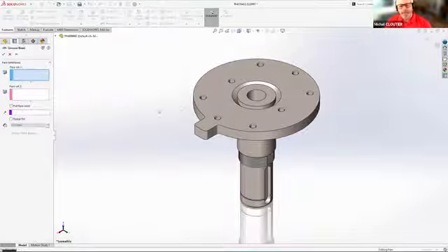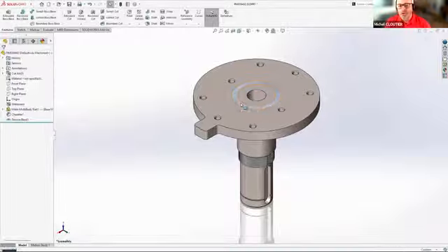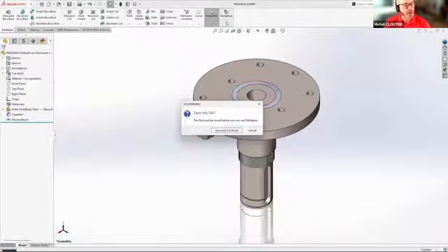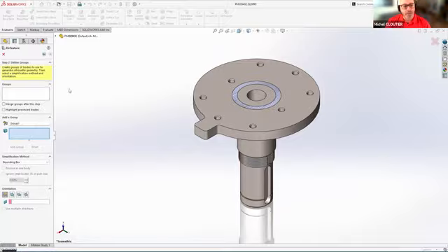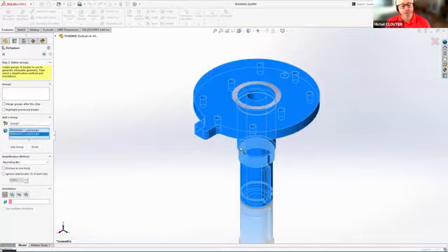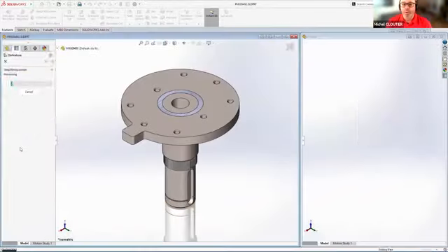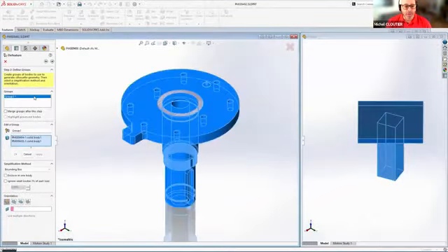Now, groove bead, I'm going to discuss that a little bit later on as well, but that's also a new feature in SOLIDWORKS 2025. But one thing that we also have in SOLIDWORKS 2025 is defeature in part mode. We had defeature for assemblies for a very long time, but now we're implementing that for part design.